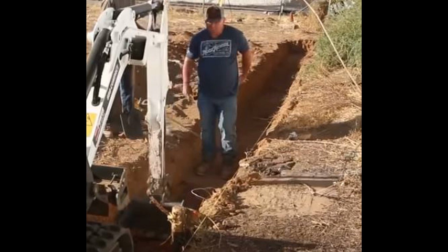However, prior to reinforcement, the presence of soft spots needs to be confirmed. Any soft spots need to be removed and backfilled with a suitable material, with the required compaction to be provided.